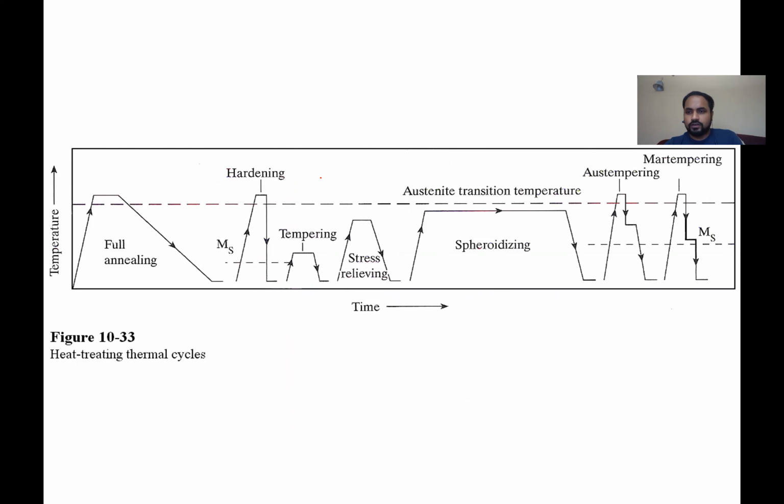Okay, so that was the iron carbon phase diagram part which you'll be using. Most of the time, you will be doing some kind of heat treatment on your steel. No matter what grade of steel you have, we will be doing some kind of heat treatment to get the optimum property. Now, the basic heat treatment that people do in a steel is shown here in the slide. This dotted line that you see is your AC3 line. So for any steel, just focus on the AC3 line.